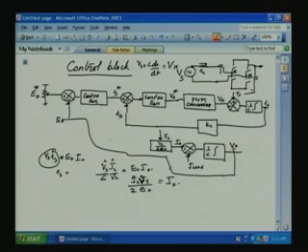Okay. Now, when the load current and the DC value of the current coming from this converter are equal, the capacitor voltage will not fluctuate; it will be steady and the controller will be in the steady state. But due to a sudden change in load, that is not in our control, this I0 can change, but our controller is giving us some steady ID. Unless VR is modified, this will not change.